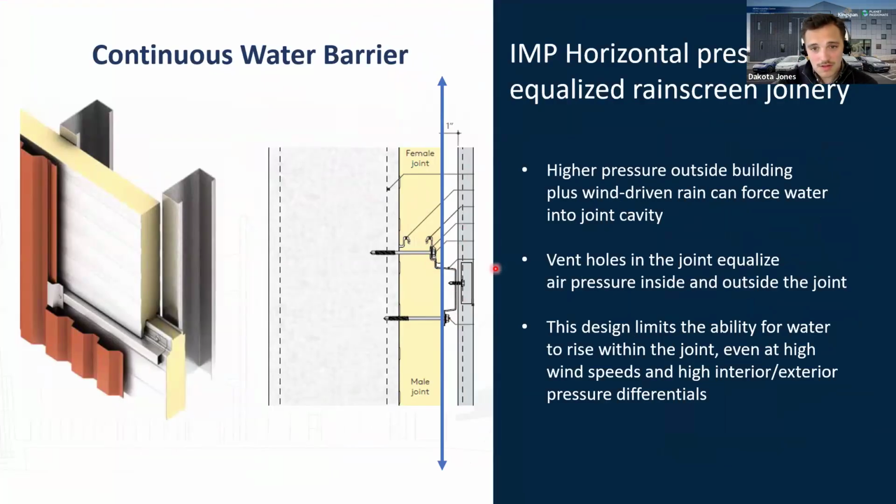This is the perfect wall. This is the rain screen we were just talking about, but way less complex. The other thing I want to highlight here is that these fasteners are going through that IMP back to the structure, meaning the IMP is actually not supporting the facade load, the structure is. As long as you're keeping that in mind and adhering to fire code, you can make this as heavy as you want as long as the structure is there to support it. In this illustration, we have the IMPs installed horizontally. They can be installed vertically as well. And then, of course, to get that airflow, because there would be an obvious guttering happening here, we have this perpendicular hat channel go there.